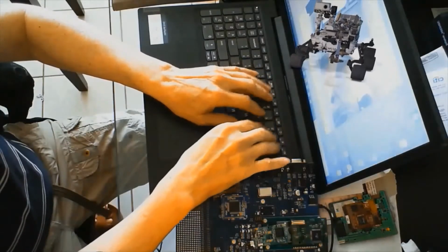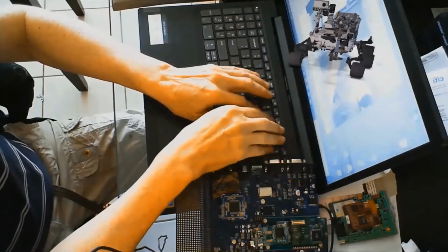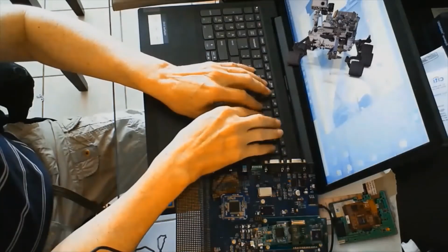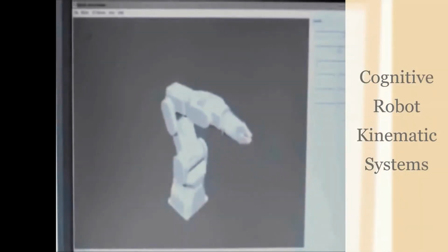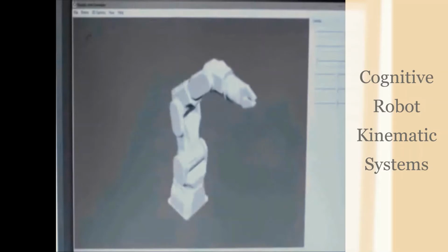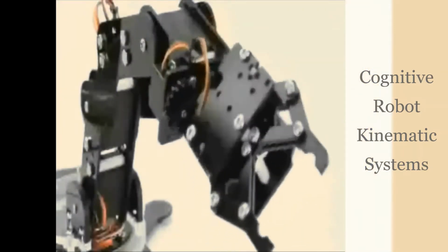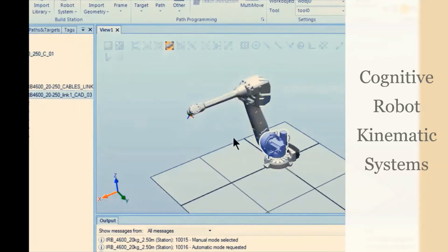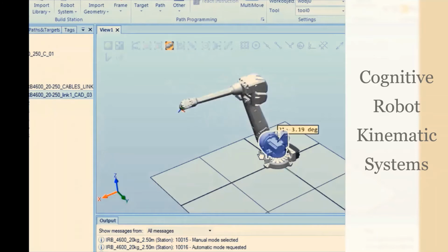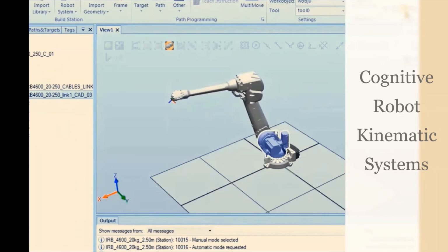The required force is constant during this assembly operation. The sensor measures the actual force between the robot and the body and compares it to the required one. The error is translated into a velocity command, which causes a motion that eliminates or reduces this error.